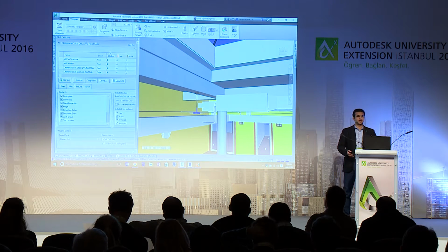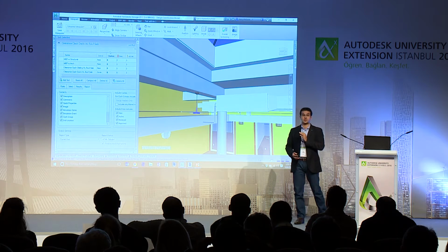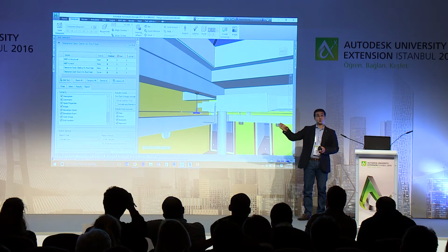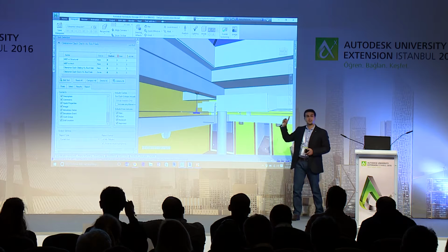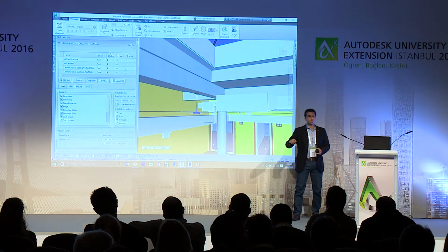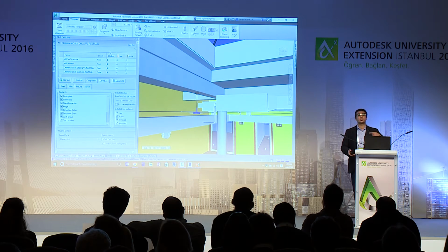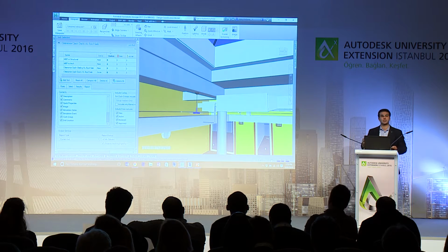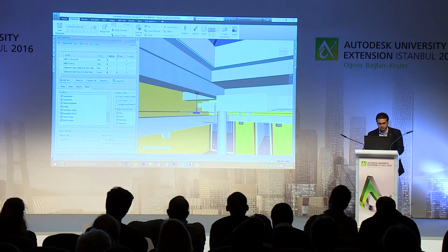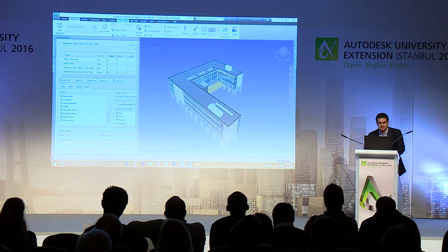And don't forget the important part, we are looking at the exact same information in BIM 360 Glue. If at any point in time, the architect who is sitting in the UK uploaded a new model, next time you open a Navisworks session, it will load the latest one. It will show you that the clash detection is outdated and you need to rerun the clash in order to find what has been resolved or if there are extra problems that have been added. OK, great. What else?